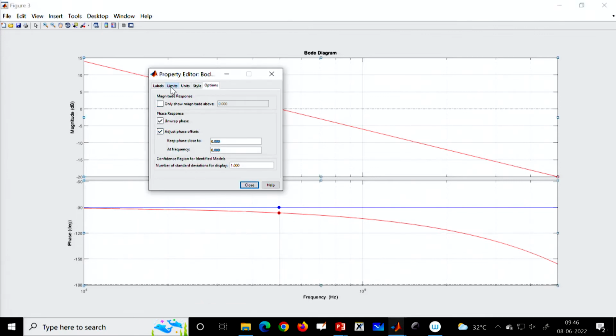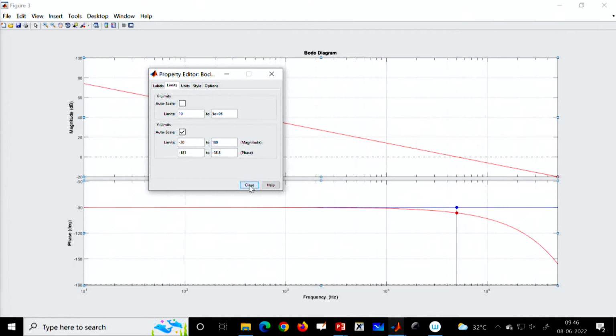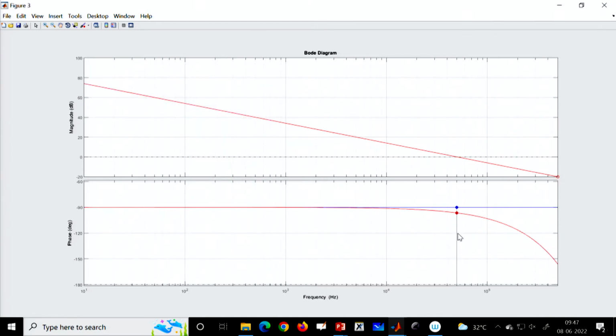So if we limit this, yes, this is what I am showing. So here is our 1/10 of the switching frequency, and you can see there is an additional phase lag, because we know for exact pole zero cancellation in analog control the phase margin was always 90 degrees, but now if we take the phase here for the digital, you are losing some phase.